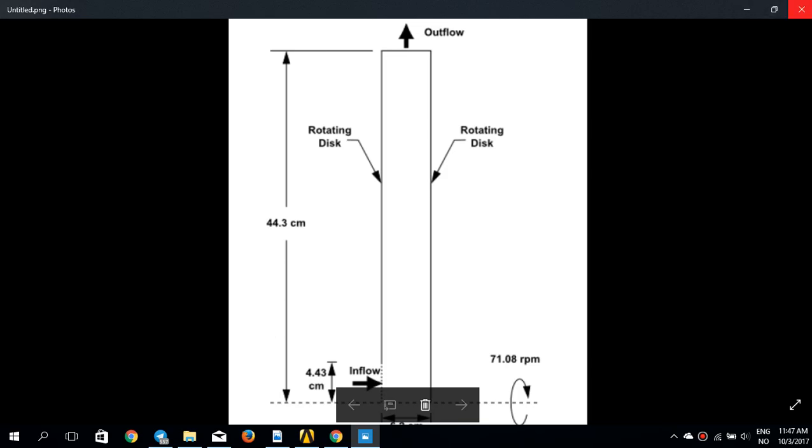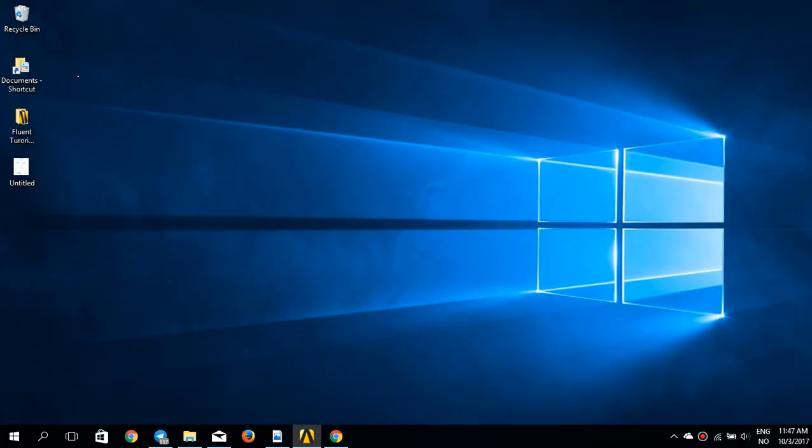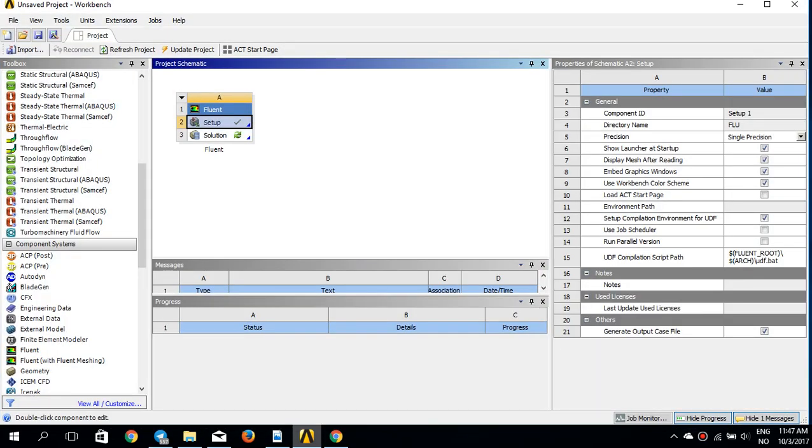If I close this problem description, we are going to set up a 2D axisymmetric model with swirl using a rotational frame of reference. Then we use the RNG k-epsilon model, and we calculate the solution with the pressure-based solver. At the end we show some vector plots and contours, or perhaps some XY plot of radial velocity and y plus.